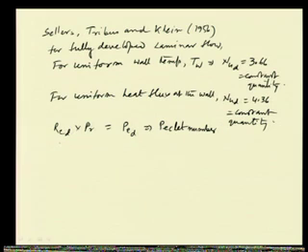So, what we get for the Peclet number expression, if we say that it is based on diameter, we can say it is like this: d V bar rho by mu into mu Cp by k. So, this gives us d V bar rho Cp by k.